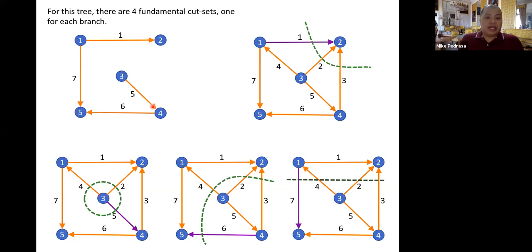So moving on, if we want to get the cut set where branch number 5 is the only tree branch, then the cut set is this one, composed of branches 2, 4, and 5. Because in these branches, branch 5 is the only tree branch, while 2 and 4 are links. They are branches of the co-tree. They don't exist here, in this particular tree.